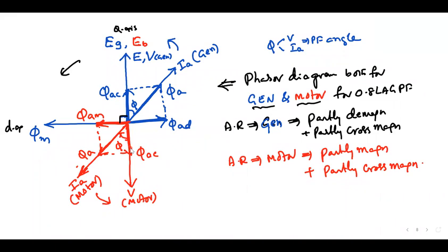Yes, sir. EB is induced EMF. In a motor, you can find the back EMF by applying the right hand rule or left hand rule? Right hand rule. Induced EMF is always right hand rule. For a generator, you rotate it and it cuts the flux. In a motor it also rotates, so it also cuts the flux.